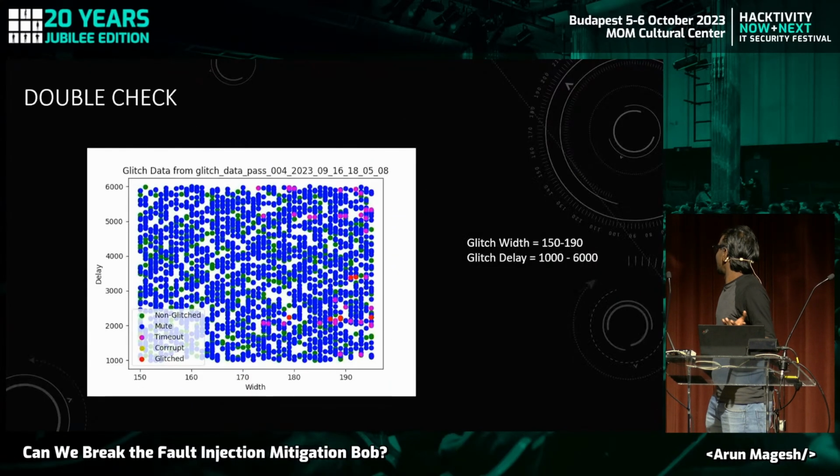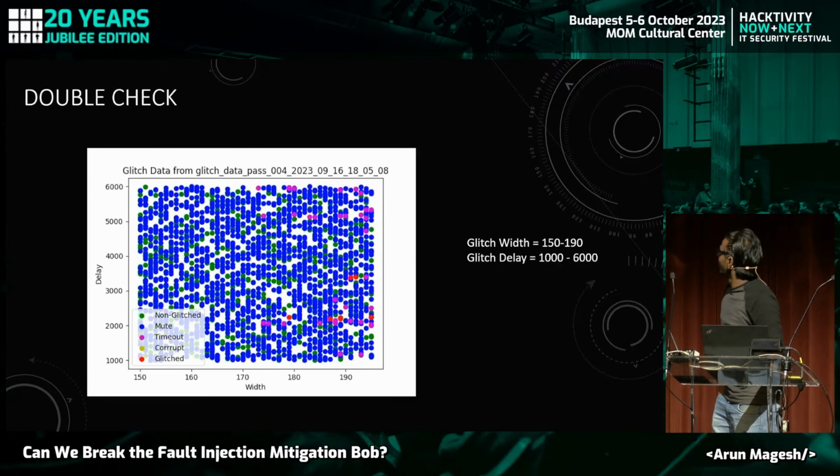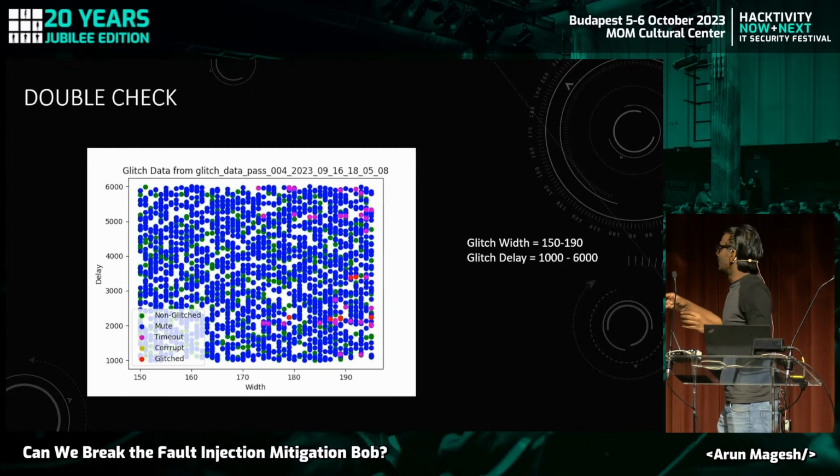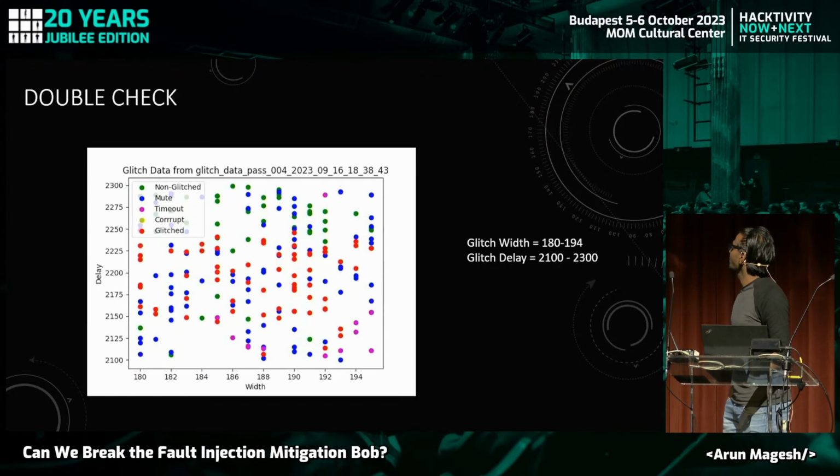And can I glitch it? Obviously, I can glitch it. You can see there are 2 sections, one around 2,000 nanosecond and one around 3,200 nanosecond, and they are in parts. In the loop, we saw that the glitches were everywhere. But in this code, you can see it's very localized towards a specific time duration, which means those glitches are from a specific instruction being glitched. That's why there are 2 sections. That's why modeling helps you understand which instruction is actually being glitched. Then, if you want to fix it, you can fix it, or you can go a bit more in depth to understand how it works. And you can just zoom into it and get more glitches.